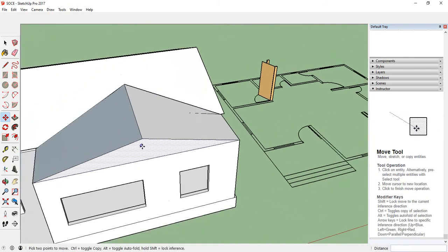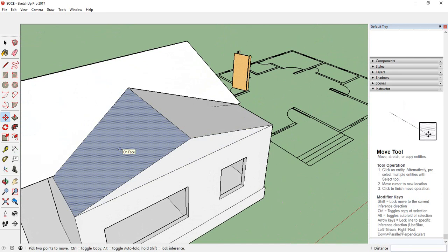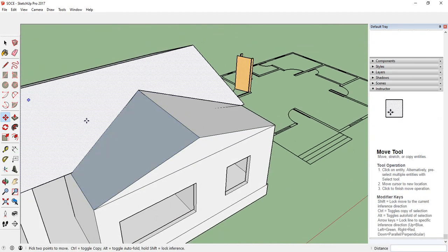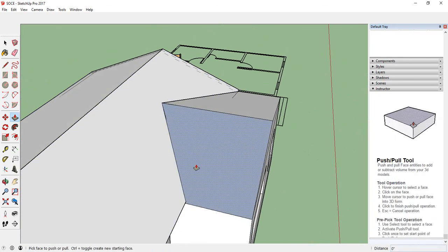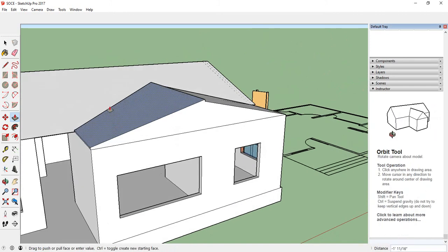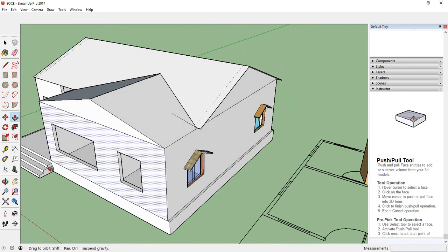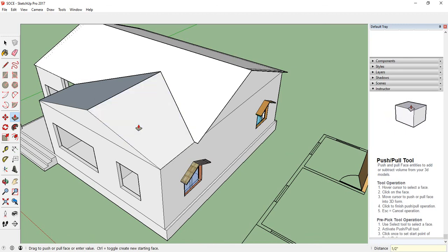When it's done, after that you are able to extrude that little bit, how much you need actually. Suppose if you just come here and if you extrude that little bit, 0.5 like as our previous, then enter, and for that also 0.5, then enter.